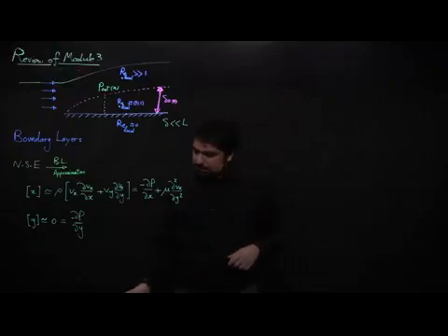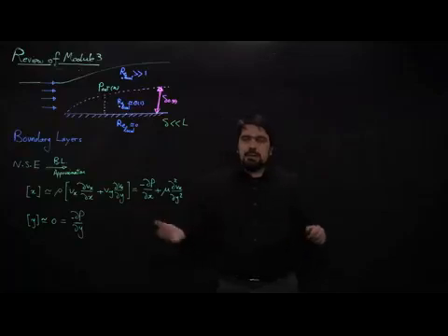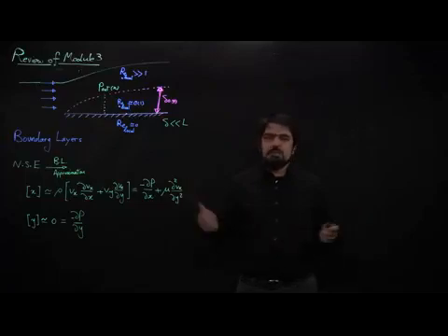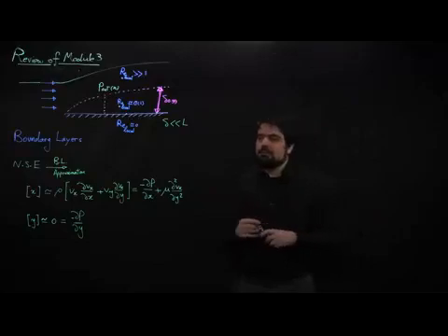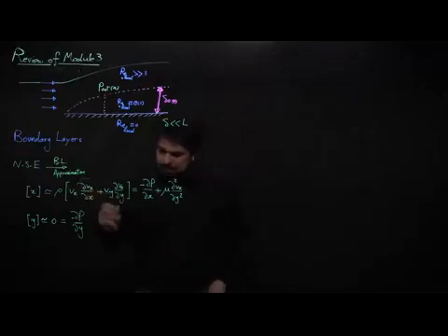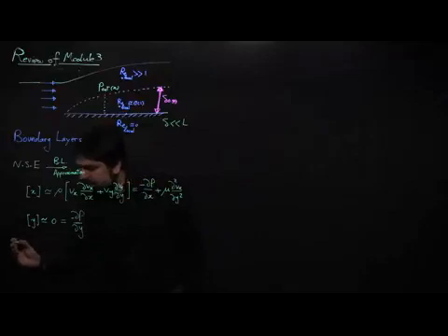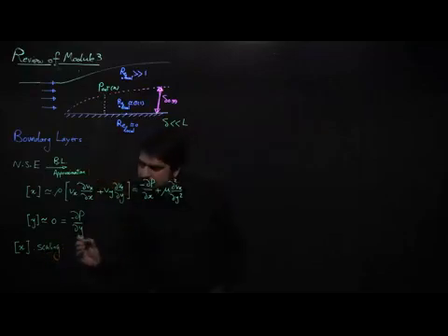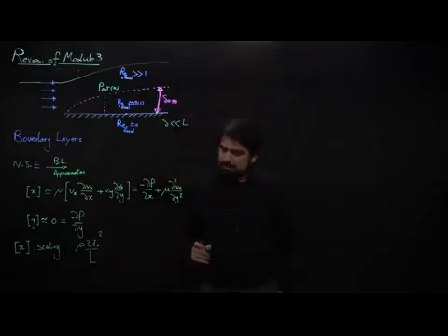Let's think about, before doing any calculations or any algebra or math, and as you have seen, this is not really easy. Blasius solution requires some numerical integration. Before doing that, let's just think about the order or the scale of different terms that we have. If you think about the left-hand side of x component for Navier-Stokes and think about a scaling of these terms, you can easily see that the left-hand side scales as rho multiplied by a certain velocity squared divided by a certain length scale, which let's say the length scale of the plate goes as L.